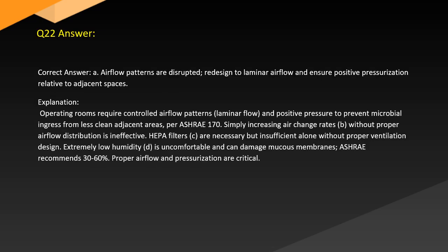Answer. Correct answer: A. Airflow patterns are disrupted; redesign to laminar airflow and ensure positive pressurization relative to adjacent spaces. Explanation: Operating rooms require controlled airflow patterns, laminar flow, and positive pressure to prevent microbial ingress from less clean adjacent areas per ASHRAE 170.